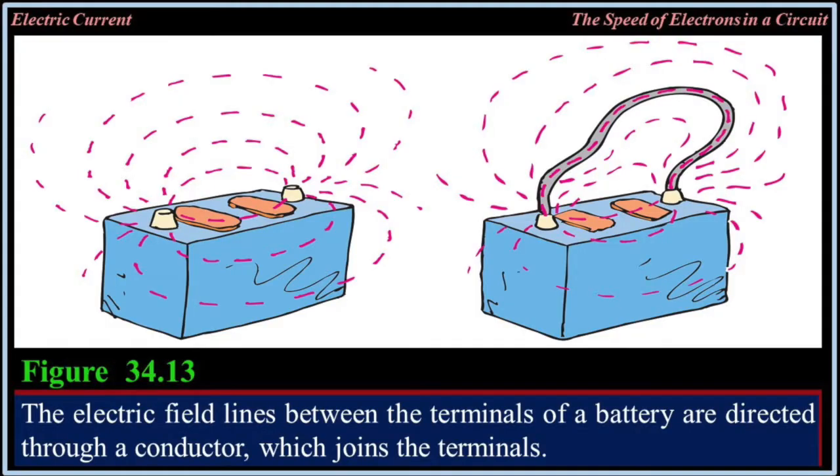Note, caution: don't short out the terminals of a battery as shown in Figure 34.13. If you touch both terminals with a metal wrench, for instance, you can create a spark that can ignite hydrogen gas in the battery and send pieces of the battery and acid flying.